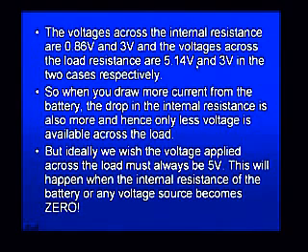Therefore, even though you apply 6 volts to a battery and you assume you are applying 6 volts, because of the internal resistance, the actual voltage applied to the external resistance will differ depending on the actual current that is being drawn in the circuit. So when you draw more current, more voltage will drop across the internal resistance and therefore less voltage will be available across the load. The load here is the external resistor that you connect.